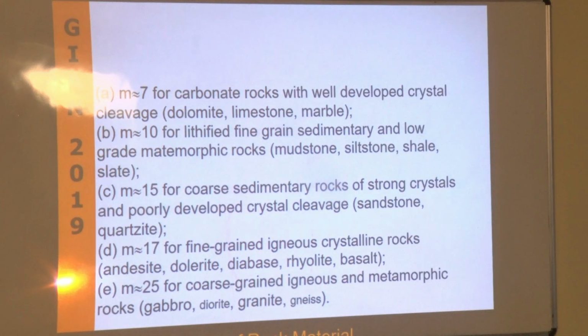So going back to the equation, m has different values depending on the rock, and generally you calculate that from laboratory tests as a back analysis. So basically it's a curve-fitting pattern, if you wish.